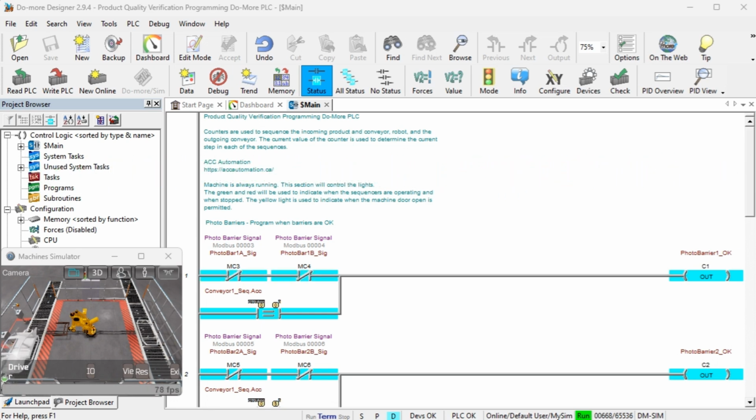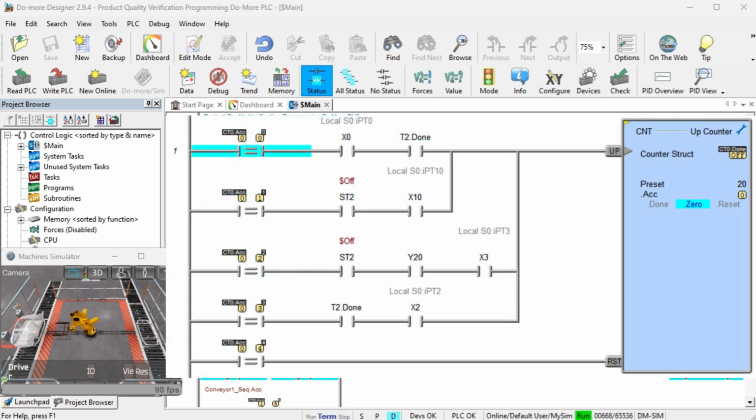Counters will be used for the sequencers in our ladder logic programming example. It is important to understand how this is achieved so that you can easily read the PLC code. Incrementing the counter is done by comparing the current count value and the conditions or inputs required to advance the counter step or sequence. After the last step or increments, the counter is reset, which resets the sequence. We can easily control the sequence when developing ladder logic code by placing normally off contacts so the counter will not advance the next step.